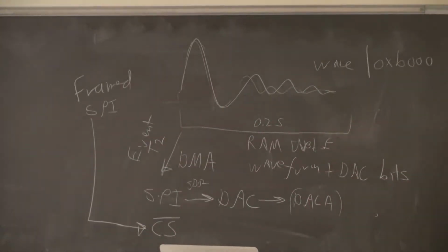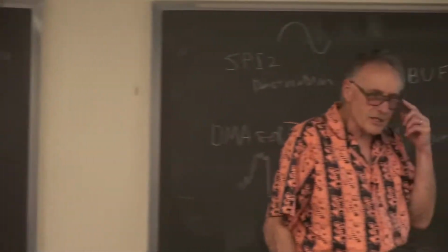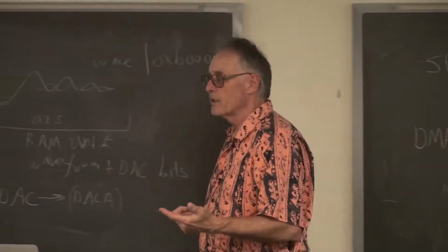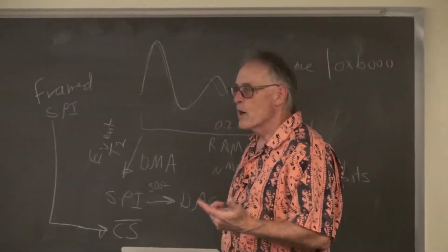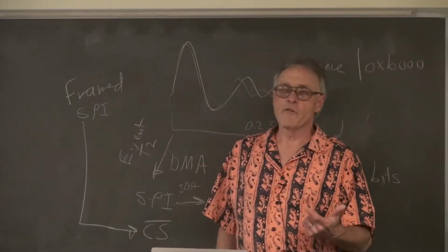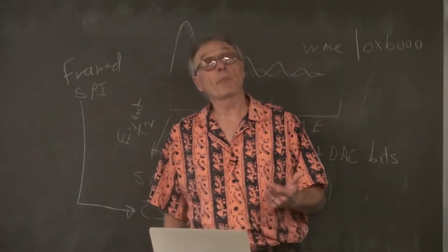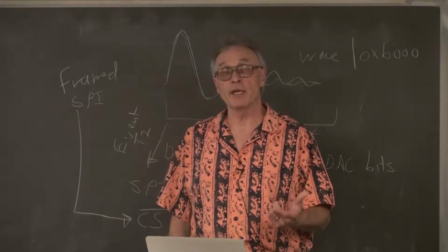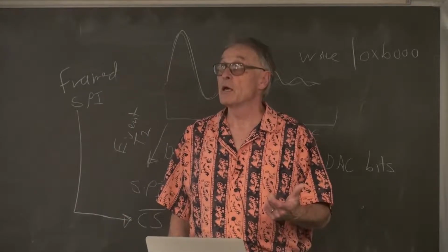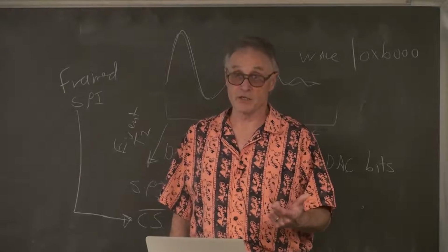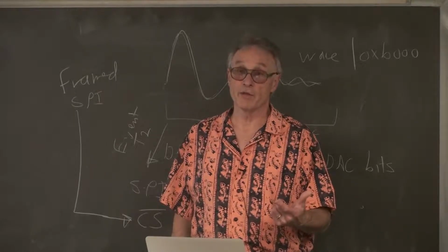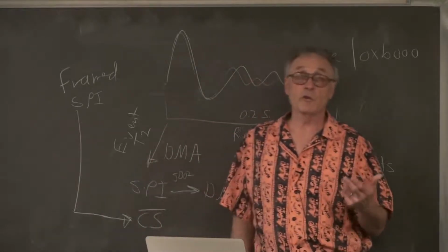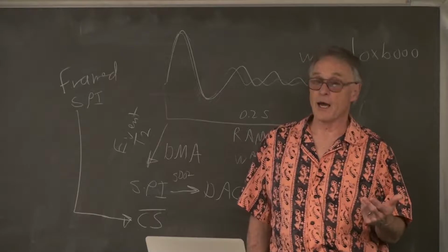Oh, interesting. So, because flash is a different target than RAM, where should you put these arrays? If you put them in flash, then the data transfer is going to compete with the instruction master of the PIC32 because you can't hit flash twice in one cycle. Do you need to hit flash twice in one cycle? I don't know.